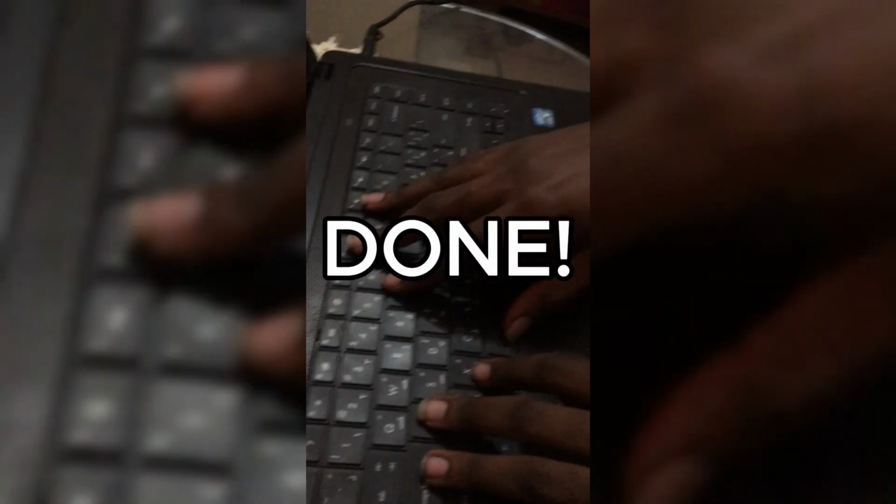Also, we can discuss the common hardware issues. We have: PC does not power on. Possible cause can be PSU failure or a faulty power cable, and the solution is to replace the PSU and check the connection. No display output is another common issue, and possible cause can be RAM not seated properly or GPU issues.